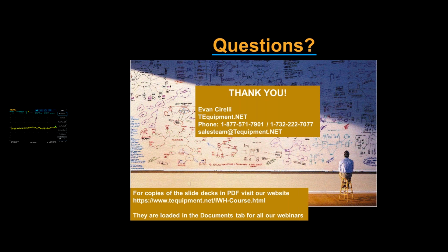So here, for instance, we've got a little peak over there at 120 megahertz. That's really the root cause of that 875 megahertz harmonic we were looking at, the fundamental clock noise. And you can see the 875 coming up occasionally.